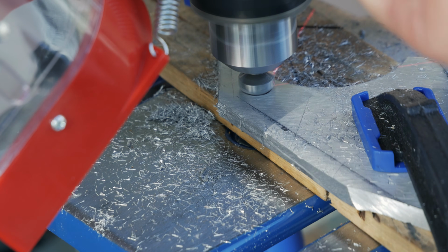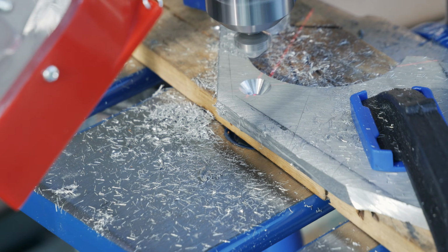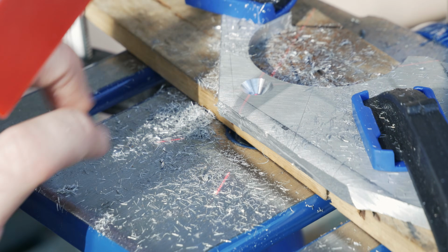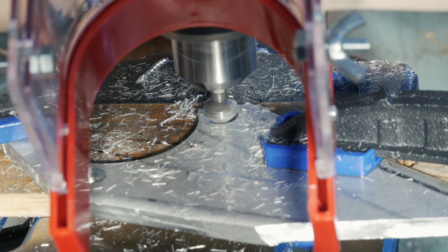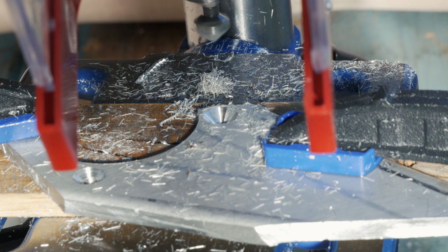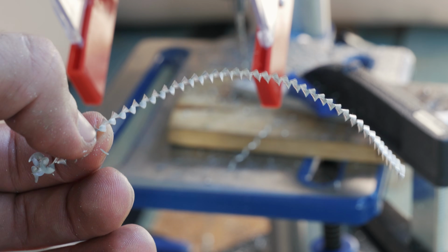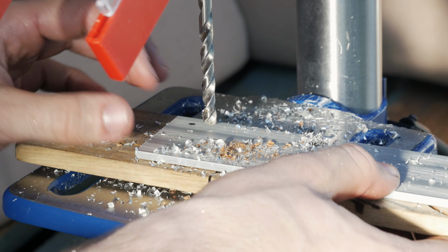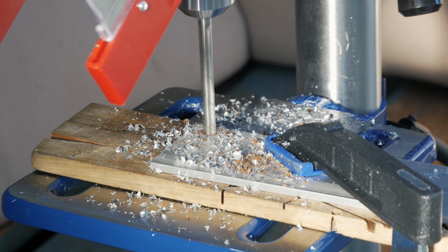I found that for the best end results with the countersinks, you want to apply very light pressure and use plenty of lubrication. This gives a really nicely shaped bore. Drilling the rest of the holes was pretty easy. I even managed to get some satisfying curly shavings in the process. Before calling it a day, I drilled 3 holes into this 4mm alloy bar. I'll use that to make the front mounting plate.